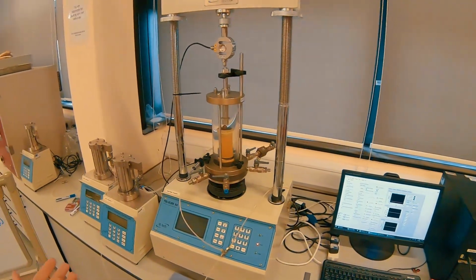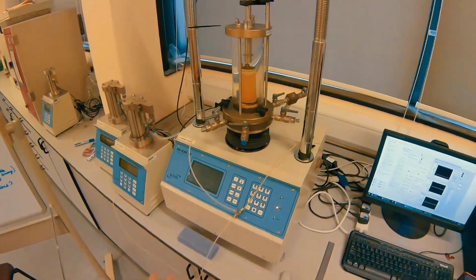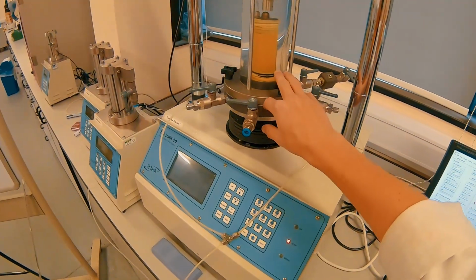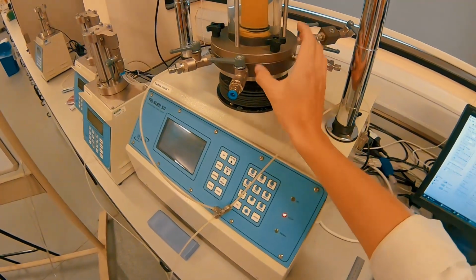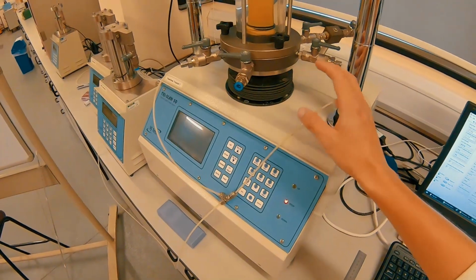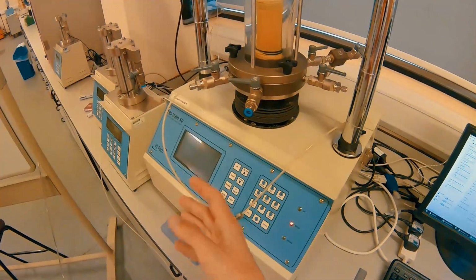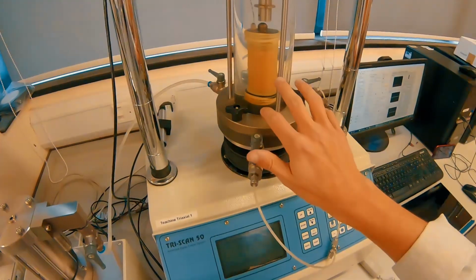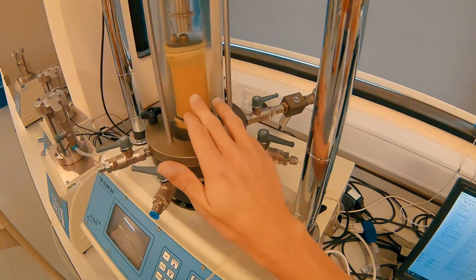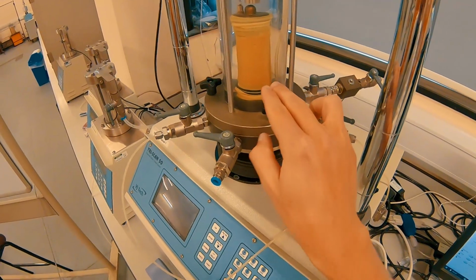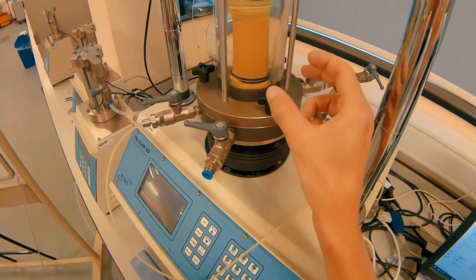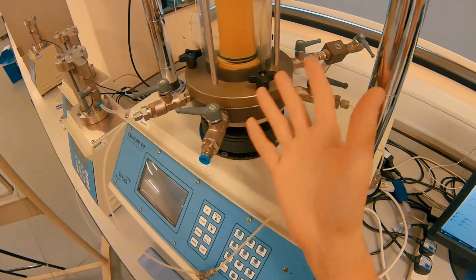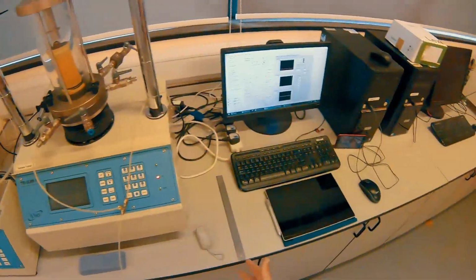So let's take a look and see if we have got our sample consolidated all the way throughout. It's worth commenting as well on the sample. If you look at the sample, you can see it has shrunk compared to a frame from the previous part of the video. It's definitely shrunk, and you can even see the pore stone there, where it's been set slightly off center from the middle of the sample, or at least the sample has shrunk inside of the diameter of the pore stone. Obviously the pore stone is less compressible than the soil. So that's one indication that there's been some consolidation.